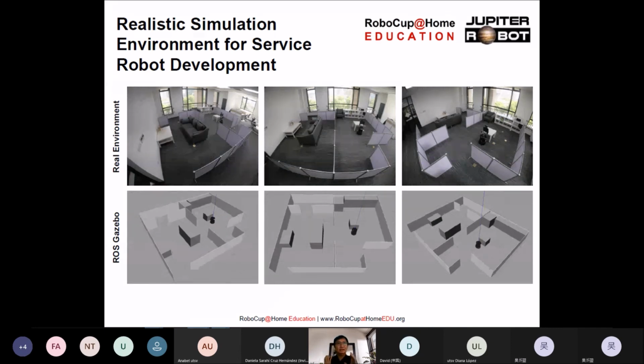You need to use the laser sensor or the RGBD sensor that gives you the laser scan, and you use the AMCL package, which I explained just now in ROS. So these are a few things that we put together, and just now you saw the demonstration of how we actually control the robot, which has the sensor on top, and we scan around and use the AMCL package to stitch the scans together.